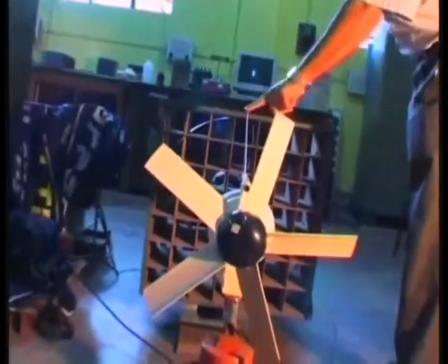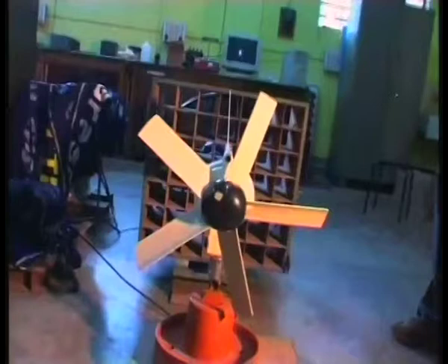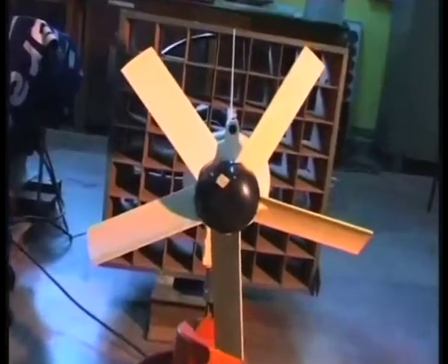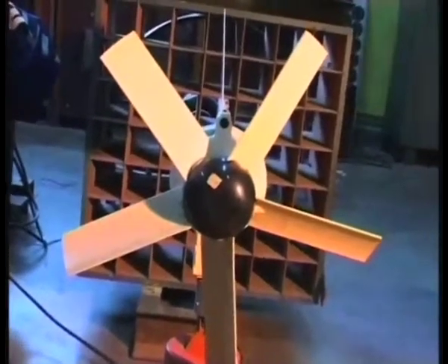So this is the front view of the model wind turbine, and normally this is not rotating now because wind is not blowing. Normally it will rotate in that direction. And here you can see the tail vane, which is used to orient the turbine in the direction of the wind. So as the wind blows, this will feel a force and that will automatically orient it to the direction of the wind. Since it is a very small wind turbine, one can use the tail vane for this purpose. For larger wind turbines, you need an automatic motor control mechanism for this orientation.